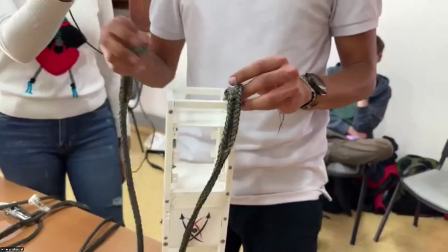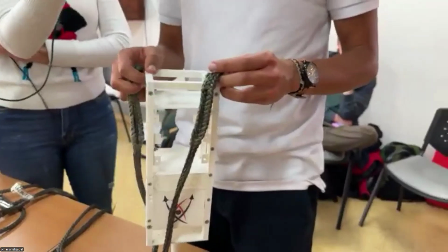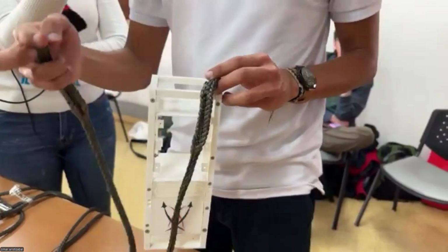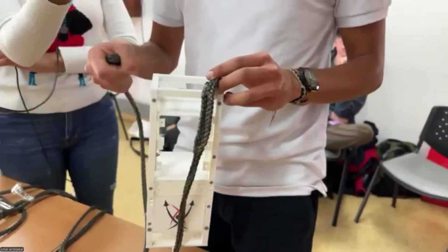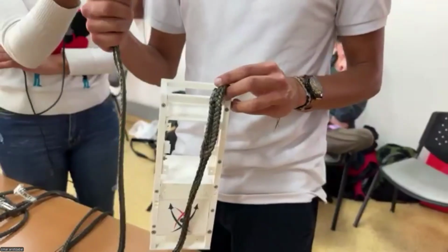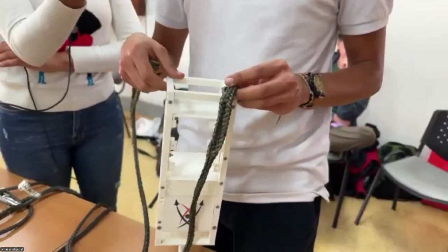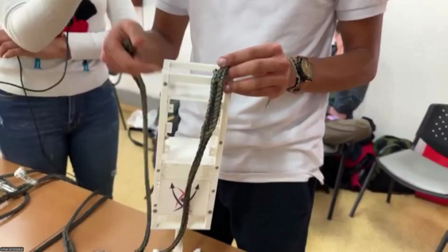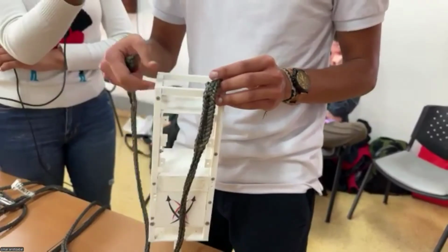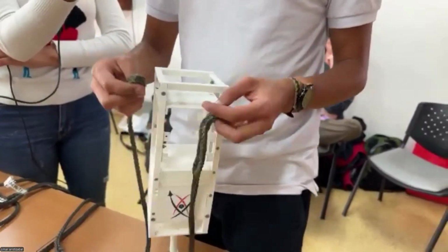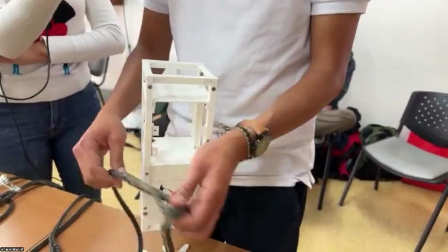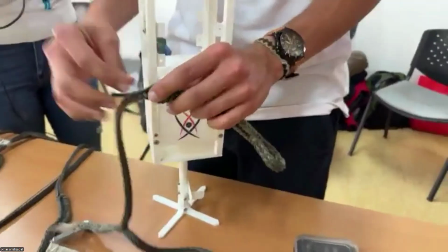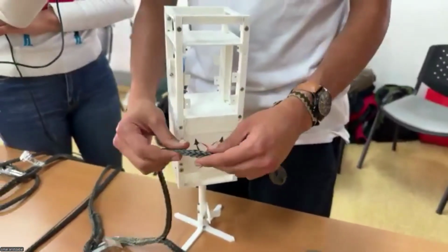So are they going to be rounded, those beams? Yeah, they will be rounded, and we will place a soft surface, for example, plastic or tape. You can use duct tape. Yeah, exactly, just to avoid the corners of the aluminum, because in fact they will be sharp, and these shock cords do not behave very well with shear force. So we want to place protection in these attachment points.